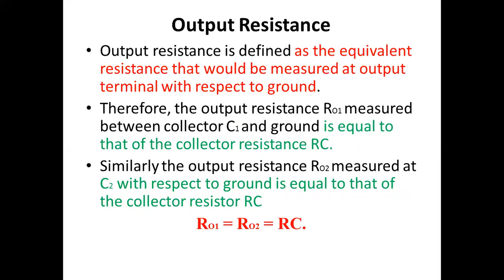Similarly, we can measure the output resistance. The output resistance is measured at the output side by keeping the other terminal at zero. Now please remember, for any circuit we build, we will be required to measure the resistance. Ideally, we should keep the input resistance infinite, so that any external unwanted source cannot enter your device.